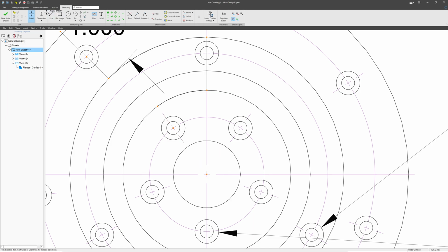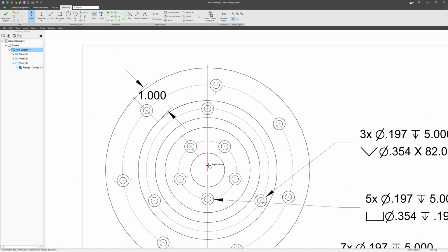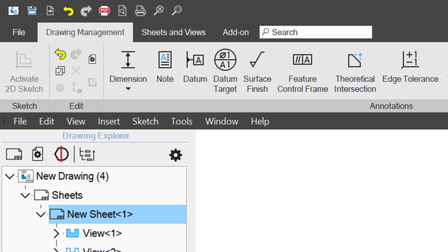Maybe I'll delete this line. And we'll add a coincident again on our point here. And also a coincident on our origin. I'll add in one more arc. We'll go with a vertical on this point and the origin. Coincident on this edge. And have a vertical line that goes to our origin. What does that buy us? Well, I'll go to deactivate my sketch.